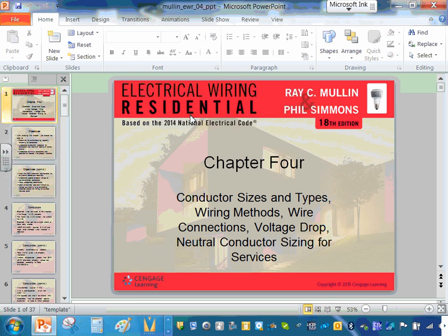It's not insulated. This guy, the more expensive cable, the MC cable, with the insulated ground, is your wiring of choice if you're doing commercial or industrial with cables. That's it. Now EMT conduit, again, if you're doing commercial or industrial, is your conduit of choice. They use a combo of conduit and cable, guys.